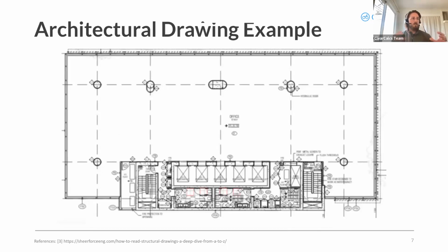You can see at the bottom there are a lot of different rooms, which is why this is the architectural drawing. It's showing us where the cabinets and closets are located, where the doors are and which way they swing open, and also the plumbing fixtures, the toilets and sinks in the bathroom. Basically the architectural drawing is telling us how this is going to look. Where are we going to place certain fixtures within the building? And other architectural drawings, not this one, would also show where the wood framing is, stuff like that.